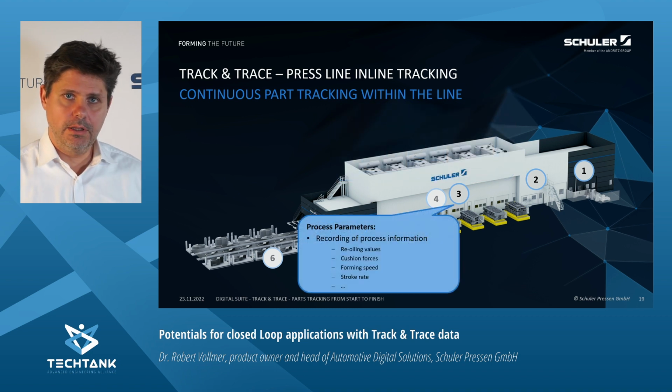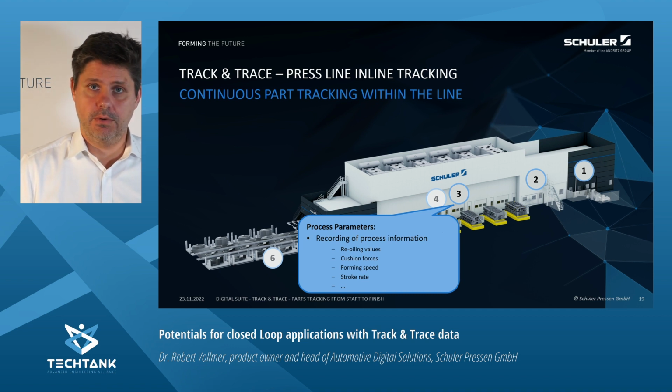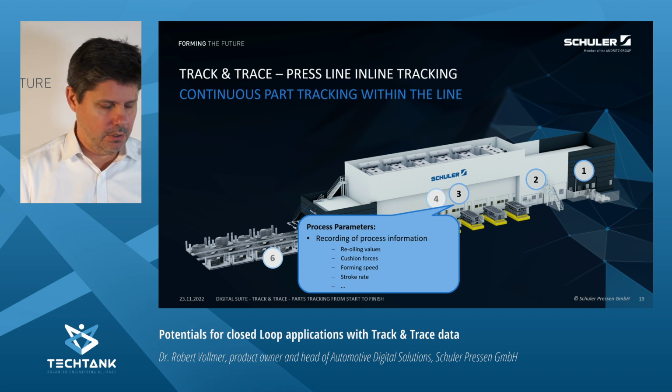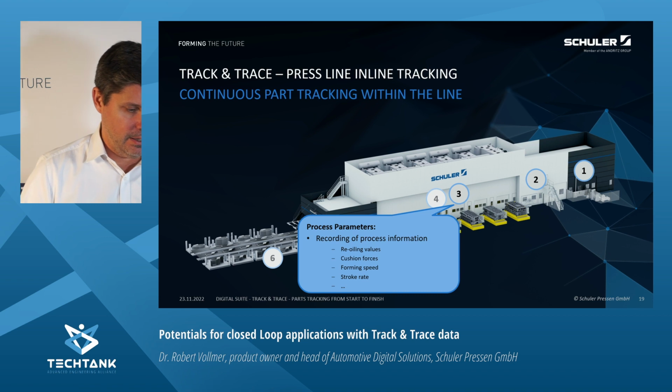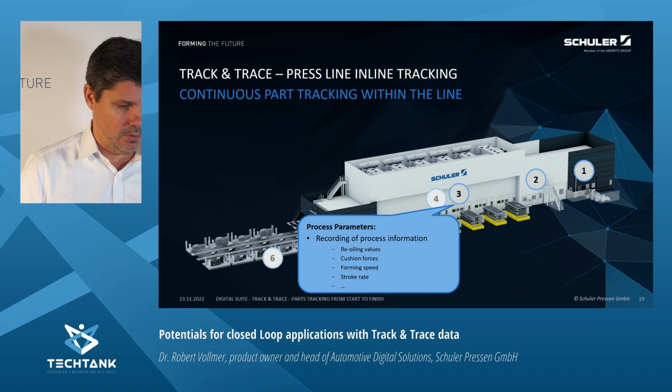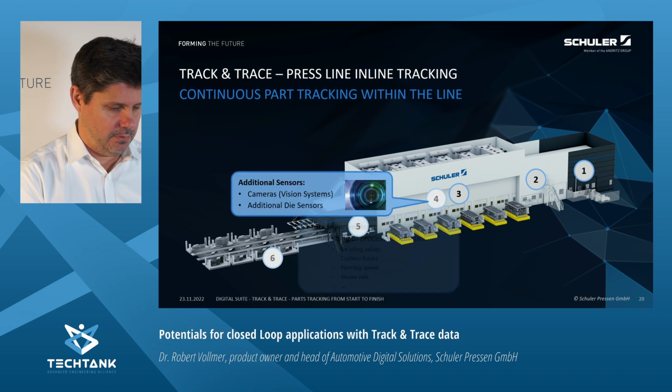We record typically all the process parameters from all the press stages which are relevant for the production. That means we have information about the re-oiling values, we have information about the cushion values, the forming speeds, and so on. We can save this information to the part ID and have again the full traceability afterwards.